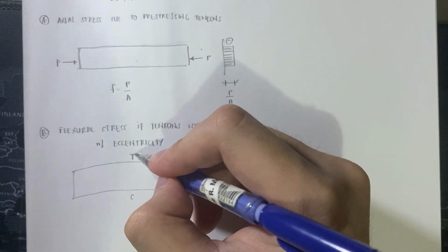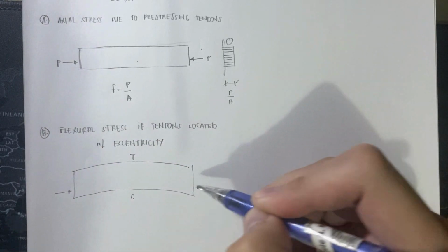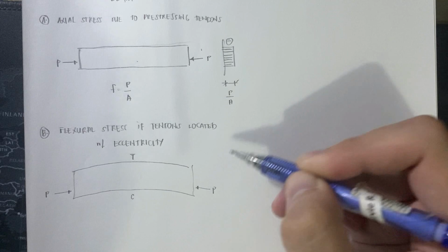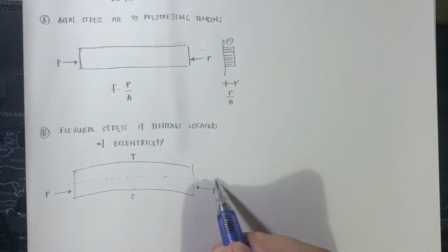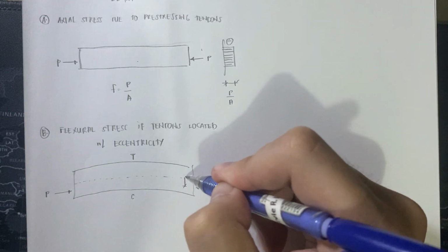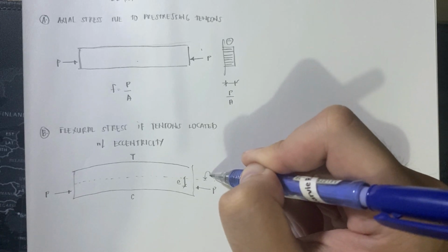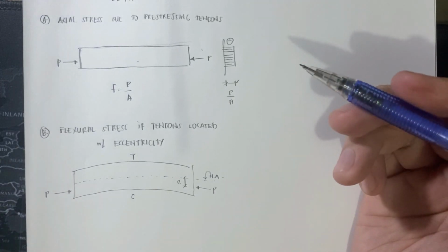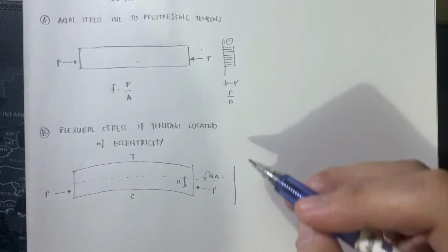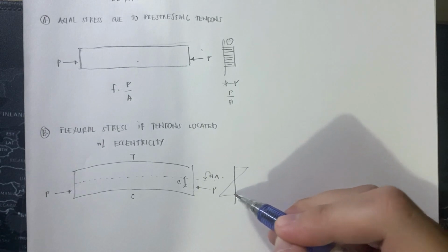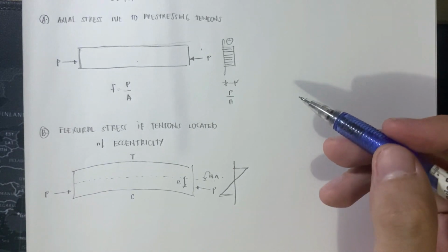From this, you would notice that our beam deflects upward, since we placed a compressive force from the lower part of our beam. So the tendency is that we get an initial displacement upward. This drawing, take note, is exaggerated just to show you the effect of our pre-stressing tendons. Take note that the eccentricity is the distance from the neutral axis to the location of the applied, transferred compressive force from our tendons.